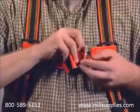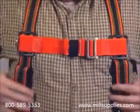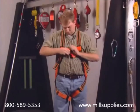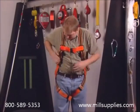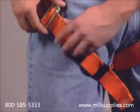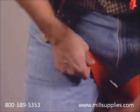Fasten the chest strap and position in the mid-chest area. Tighten to keep shoulder straps taut. After all the straps have been buckled, tighten all buckles so that the harness is snug, but allows a full range of movement. Secure any excess webbing by tucking it under loop keepers. To remove the harness, reverse these steps.